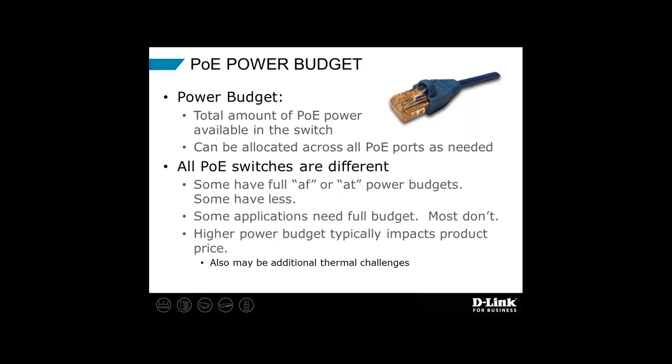Now, all PoE switches are different when it comes to power budget. Some of them actually have what would be called a full AF or a full AT power budget, meaning full AF, which is 15 watts, meaning it could concurrently power 15 watts across all ports. AT, a full AT switch, would be 30 watts across all ports concurrently. A lot of PoE switches have less than that in their budget.